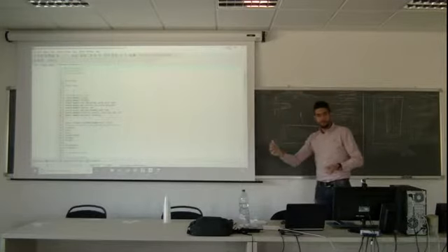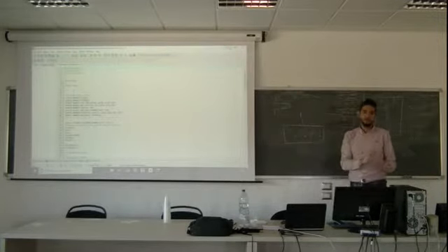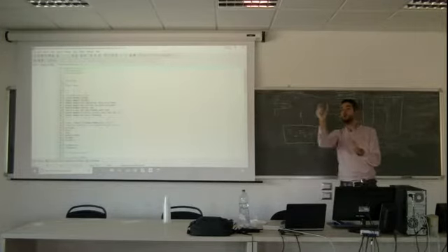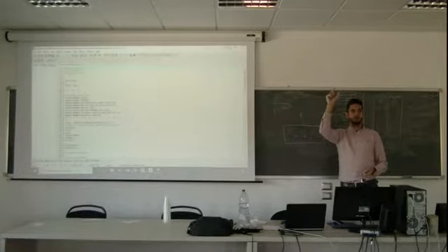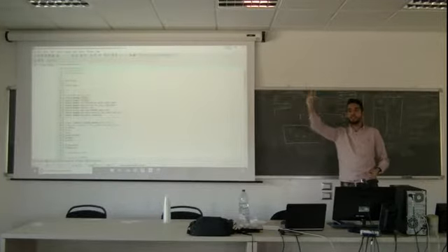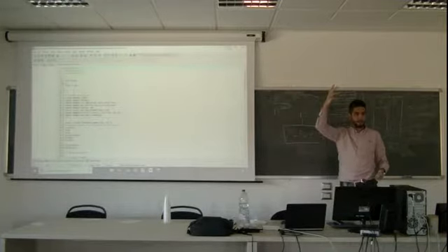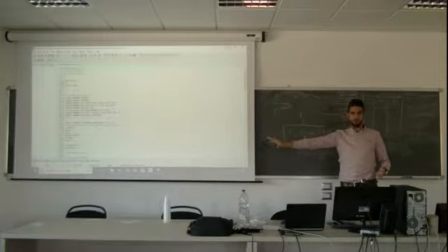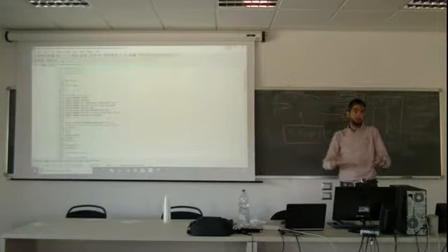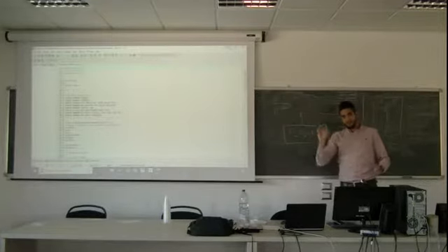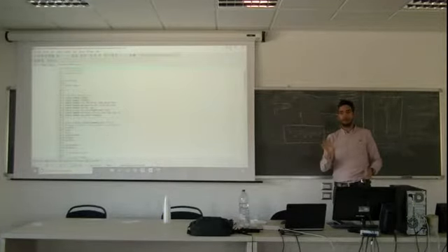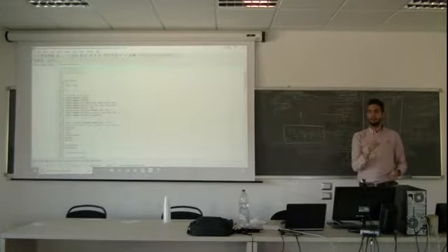So it's getting complicated. If you apply this physics, then the problem is not that simple, because for each iteration you assume one temperature of the node. For each node, you will have a different heat transfer coefficient, because you will have a different Nusselt number, because density is different, viscosity of the air is different, everything is different, because the film temperature, meaning the average between solid and air, is different. Don't worry, the computer will compute for you. You just have to program it. But that's a good example of how a good assumption can give you a good benefit.